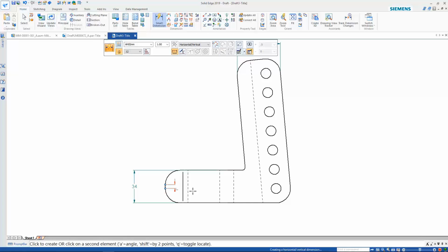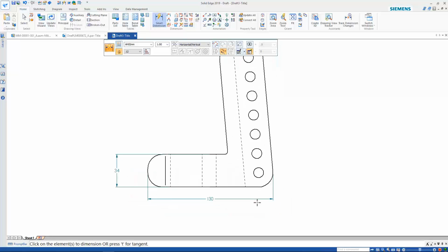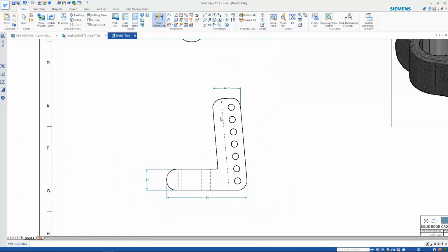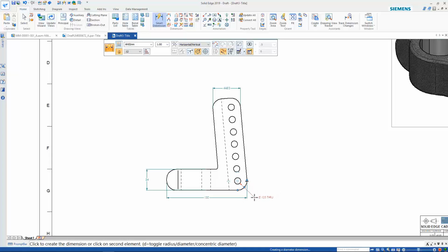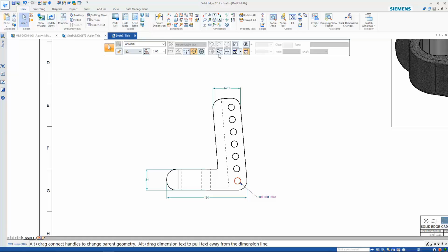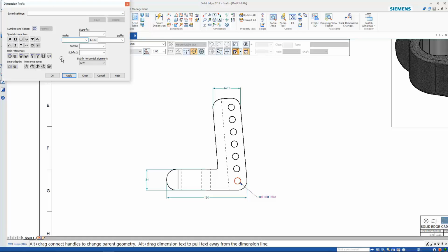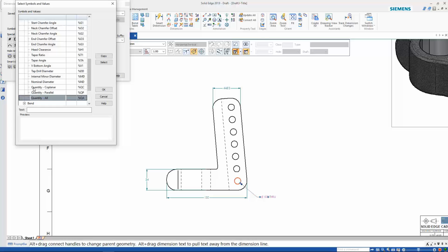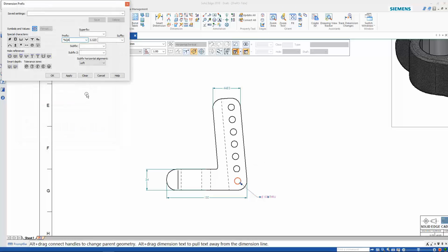So I'm just going to select what I want. Select the different points to make sure we get those dimensions that we need. We can select that on there. I've got an option for a hole callout, so that's going to pick up that hole for me straight away. I've got 7 of those, so I'm just going to go into my option and add a little option on there, or I can say coplane. Yep, so that's quantity all of those.